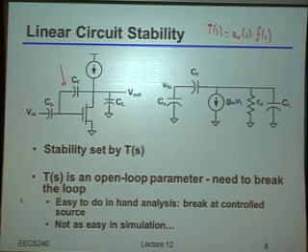Yeah, exactly. You don't want to change the loading, right? Because if I break it at a node that's not high impedance, and by the way, here high technically should mean infinite, right? If I don't break it at an infinite impedance node, then I will mess up the loading. Okay? So we're going to say a lot more about that in 1 second. Oh, yeah, question?